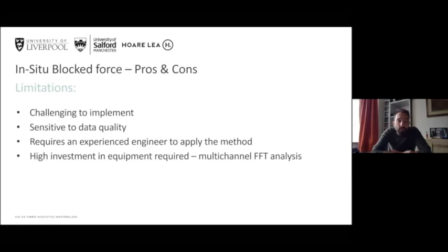Again, I've mentioned already that we also need to have a high investment in equipment, which includes multi-channel FFT analysis, multiple accelerometers, force hammer, instrumented hammer or shaker, and probably some software modules that you wouldn't normally have on a sound level meter. So good results, but challenging and expensive to implement.